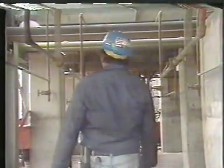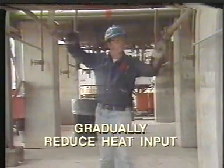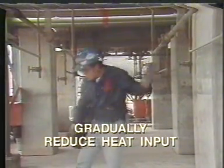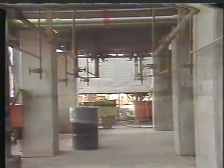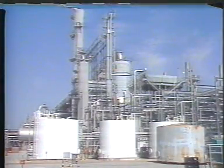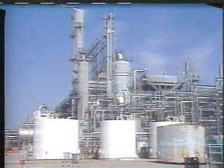The next step is to gradually reduce the heat input to the tower. In vacuum columns, the vacuum is taken off and the column is shut down under atmospheric conditions. As the temperature in the tower decreases, light components fall to the bottom of the column and mix with the heavier material. This liquid mixture is pumped out and saved for reprocessing.